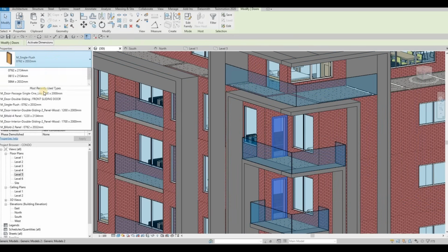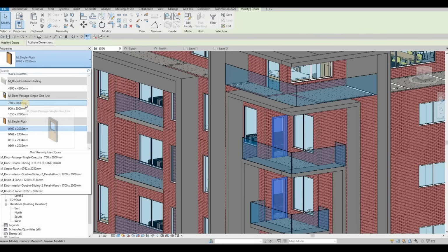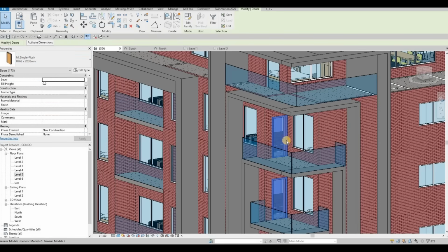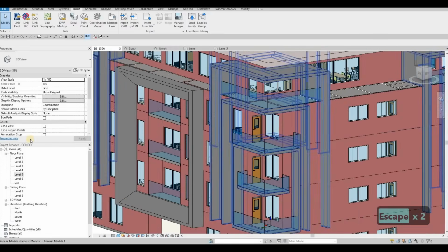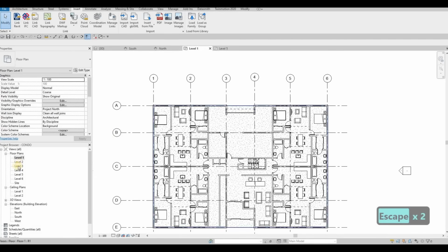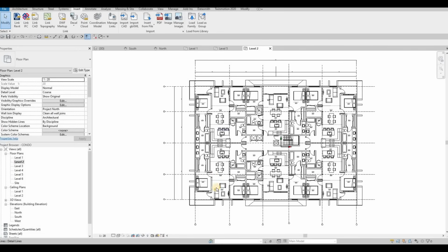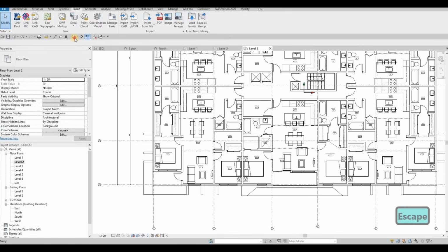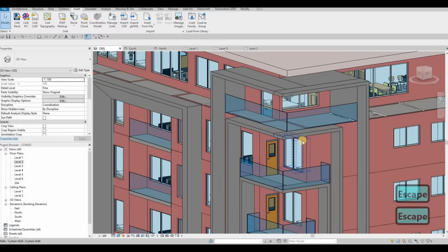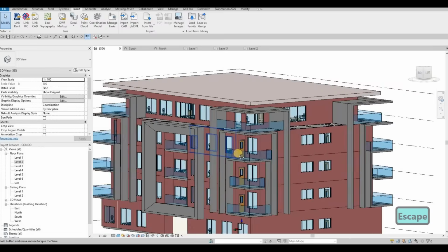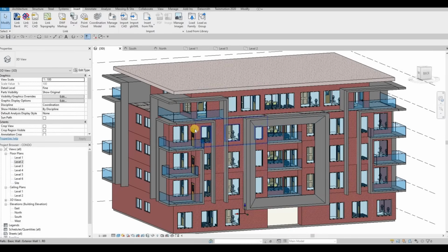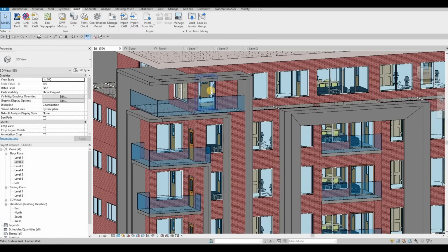that's 700, so we're gonna choose 750, so something like that. And as you can see, there's a handle there, so that looks nicer. Okay, orientation is good. It didn't change, it just changed the look of the door to a much better one. We can also change the door right here, but I think a glass door is nicer here.